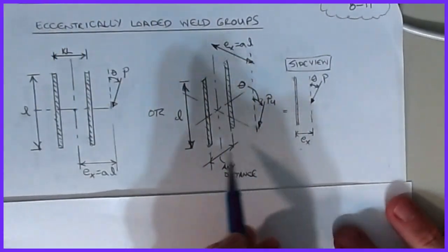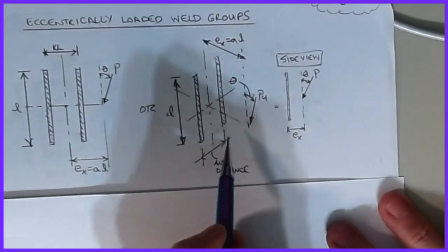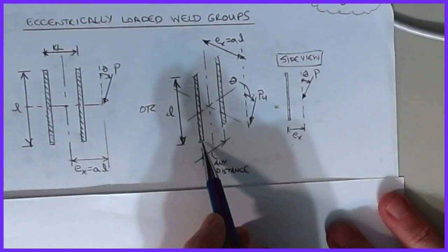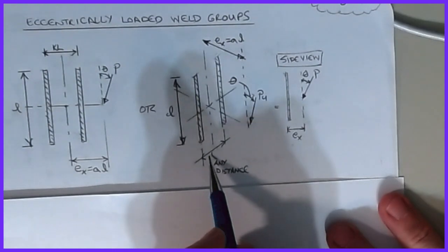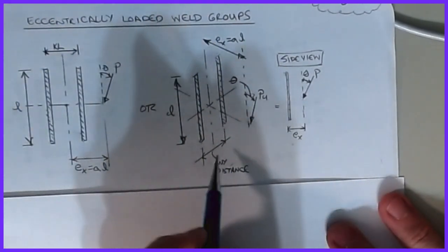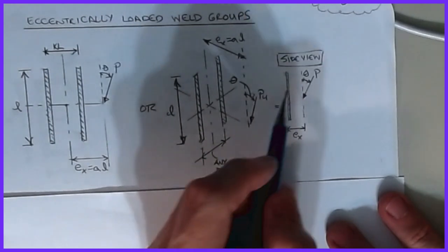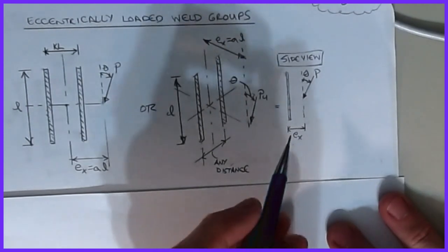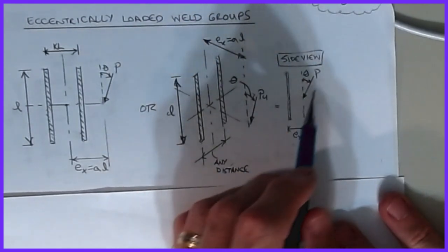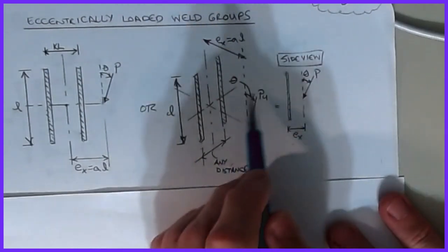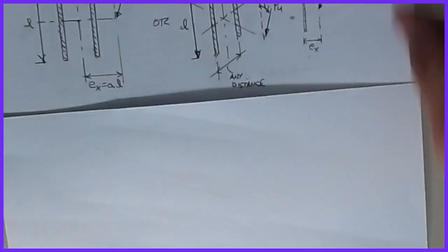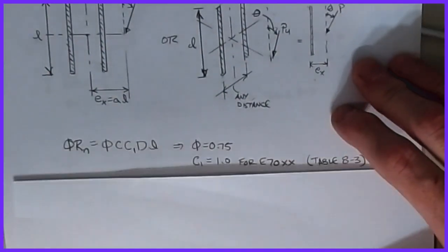So what I tried to do, and the picture's not totally obvious in the AISC manual, it's a little hard to deduce, but you'll notice a couple of changes on this one. One is that any distance will work on this. Where it was KL before, now it can be any distance. And then if I look at this from the side, this is the arrangement of what we have. I have a weld, and then a distance into the page is another L weld. So they're all on the same line, and then this is the load happening in that perpendicular plane to the plane of the welds. So just be advised of that. But again, we've talked about A's and K's and all that, and I'll show you the example to try to deduce that as well.